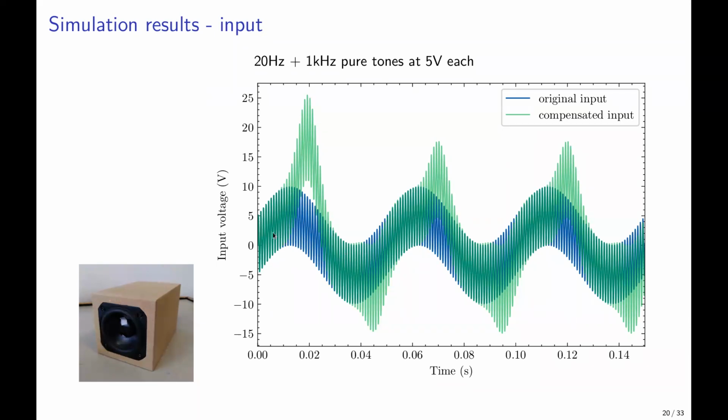You can already imagine why it has to be really high here, because the low-frequency excursion will be really high, and probably something hinders the loudspeaker from moving as far. For example, the spring gets stiffer the further you move out, or the force gets less because the coil moves out of the air gap.